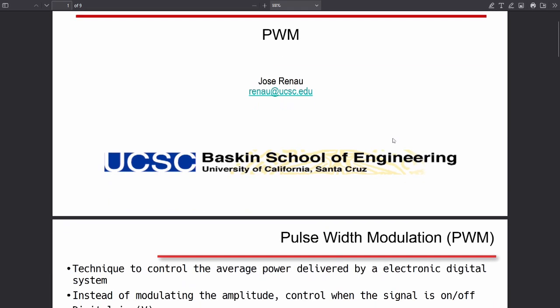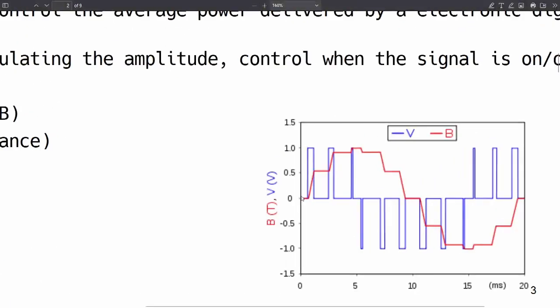The idea with pulse width modulation is that here you can see this analog signal, this red signal right here. If this is our desired output, unfortunately we can't actually create this red output, but maybe we can provide this blue output. If this is some sort of audio signal, maybe we are trying to drive some sort of speaker, and in order to do that, we would instead send pulses with a certain width. Maybe this pulse is sent for 10% of the time, and this pulse is sent for another 10%, and then this one is really skinny, so this is 5% of the time. And that is how the analog write pins often work on microcontrollers.